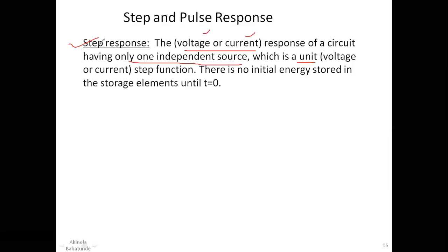And then, when we have just one independent source, and we have a response that is a unit, either voltage or current, we refer to that kind of response as step response. There is no initial energy stored in the storage element until t equals 0, unlike the previous analysis that we've had, where you already have initial charge before you turn the switch on. All right. So in this case, there is no initial energy stored in the storage element until t equals 0.